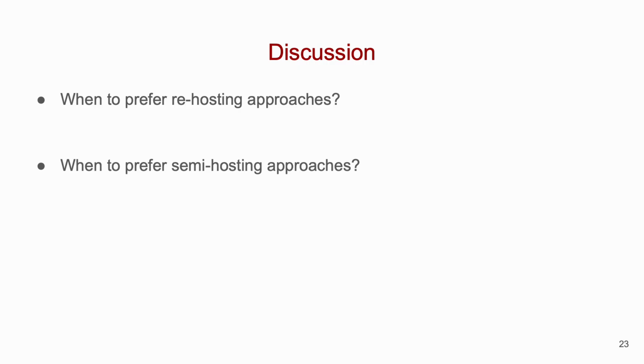So, when do you think semi-hosting outshines rehosting? When fidelity, observability, and compatibility are preferred over scalability. Semi-hosting allows true responses from real hardware and supports testing of complex peripherals with high fidelity. Although semi-hosting techniques currently offer lower speeds compared to software emulation approaches, they are the only methods that allow testing of complex peripherals.